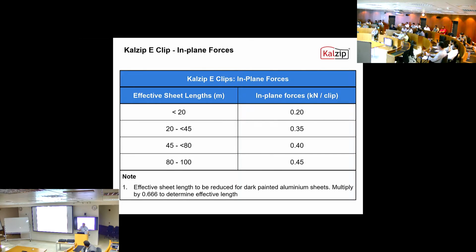So you're looking to reduce the amount of movement. So you've got two roof lights. You could put the fixed point between the two roof lights, so you're still reducing the amount of movement. The detailing around the roof lights, you need to consider that. You need to make sure that the upstand of the penetration coming through the roof and the upstand with the cowl zip penetration, there's enough movement to allow that to freely move.